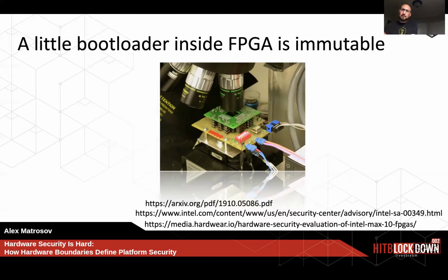Any FPGA chip also has a tiny microcontroller on it, a bootloader inside the silicon, and it is unpatchable. The vulnerability found on the Max 10 FPGA is split between this silicon-based bootloader and some other stuff, and that means it is a silicon issue which is hard to patch in the field.